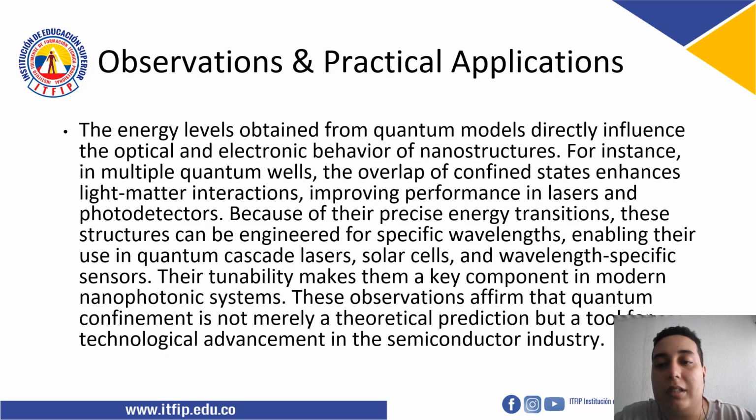For instance, in multiple quantum wells, the overlap of confined states and the choice of material interaction improve performance in lasers and photodetectors because of their precise energy transitions. These structures can be engineered for specific wavelengths, enabling their use in quantum cascade lasers, solar cells, and wavelength-specific sensors.